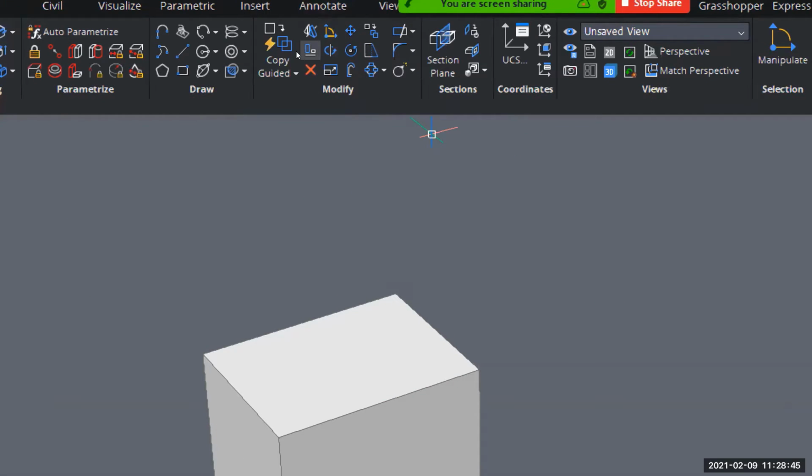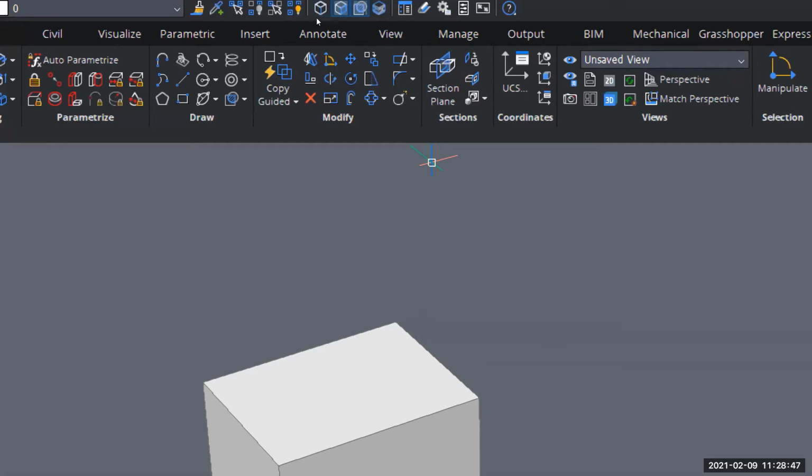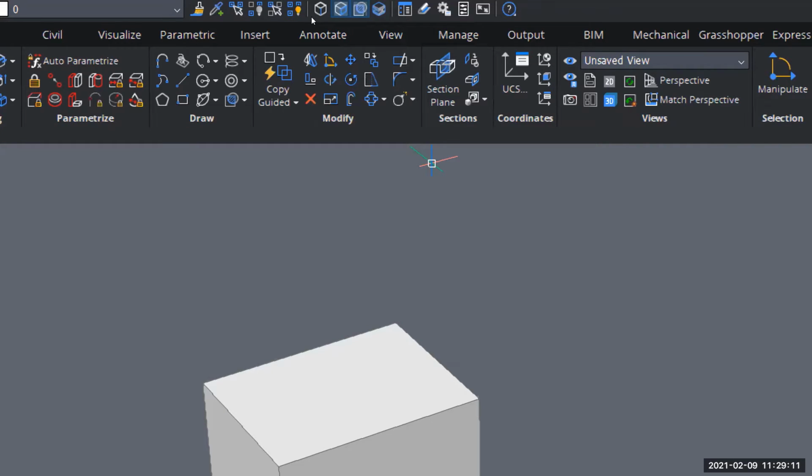we have these little 3 icons here. And if I hover, you can see the little tip that says enable the boundary. So this one right here enables the boundary detection. Here I enable the face selection, and here is for the edges. Often, if I'm just doing pure 3D, and I'm not starting my model from 2D entities, then I make sure that everything is off.